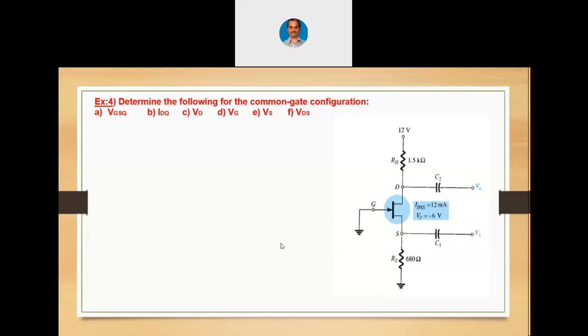Why? Anyhow, the JFET does not require any gate current for its operation, unlike BJT. In BJT, it was very much essential to connect two power supplies, but in JFET, strictly speaking, we may not require VSS at all, as is evident from this example, because there is no need of any gate current. Only thing is the gate needs to be reverse biased for bringing the JFET to the middle of the transition curve. That is anyhow going to happen because of the connection of RS.